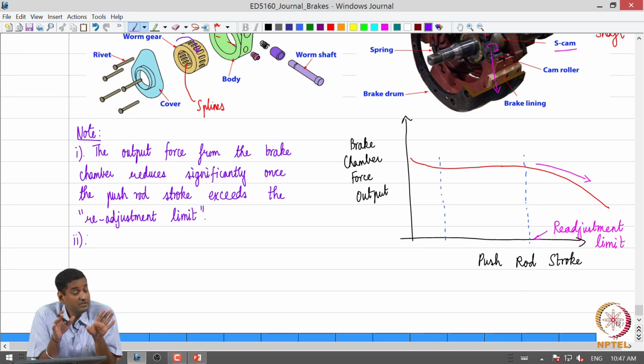That is a result of the fact that we are losing brake fluid there, right, and we are losing that fluid pressure. So the reaction that comes to the driver is reduced. What was the physics behind it? The physics was due to the mechanics by which the hydraulic brake system functions. There the brake fluid is pressurized by the human force.